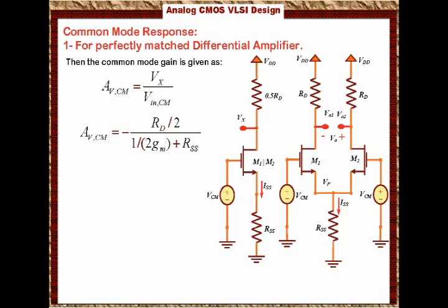So what we have said so far is that if we have a common mode input voltage and the circuit is exactly matched, then this common mode voltage, if it's AC, will swing at the output. So we will see the same common mode voltage swing at the output. Vout1 will have it and Vout2 will have it, which is something that makes sense. Now we know how much the voltage will swing due to the common mode input voltage if the circuit is exactly matched.